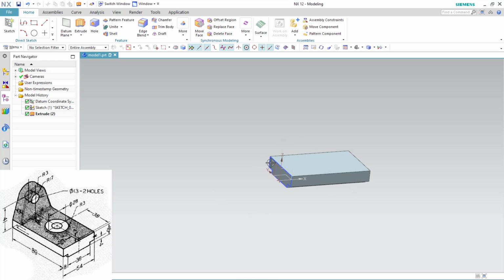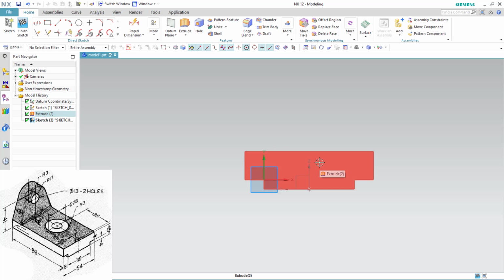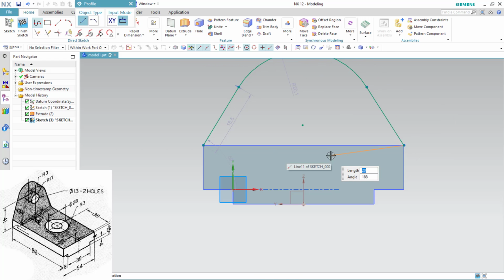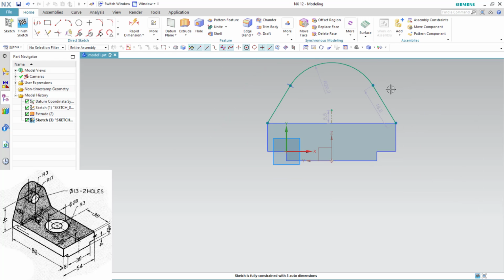Yeah, so next thing I need to draw this portion, so I'll use this face as the reference. I'll use the same profile tool, switch to arc and draw it like this. Close the sketch. It is still open. Yeah, I'll draw the vertical line because I can make it vertical. The sketch will be at the center, no, like this. Convert this to construction, done.